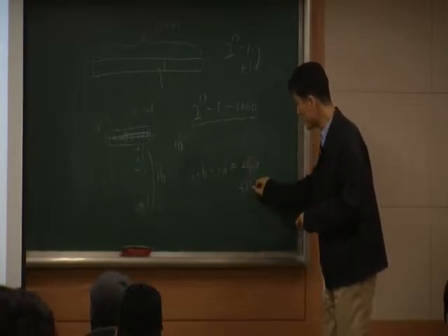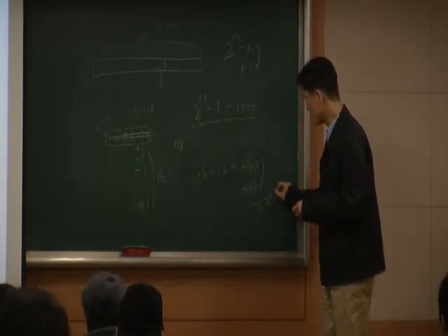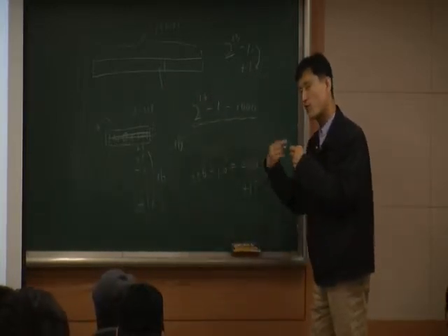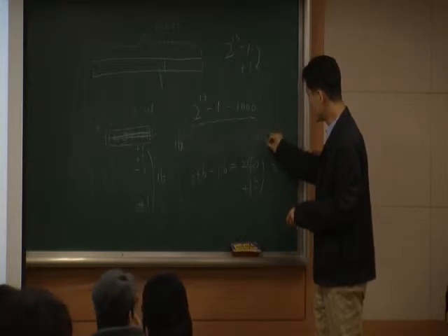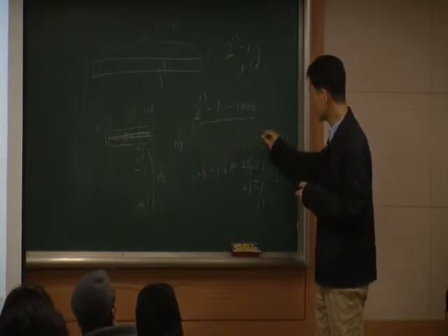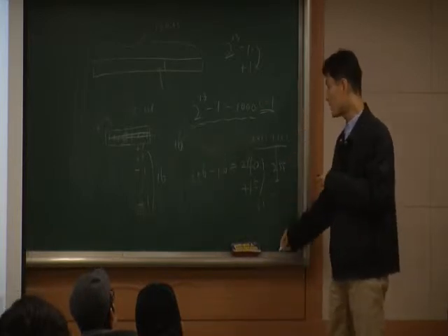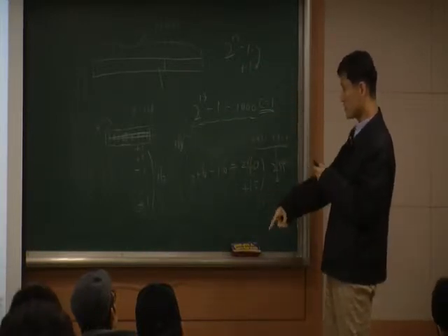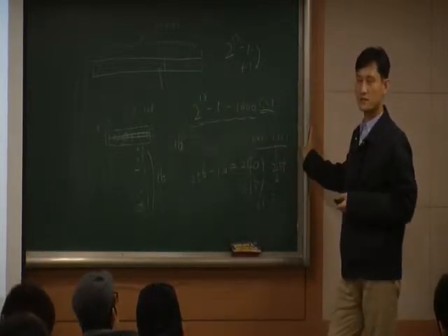So once you have 16 pulses coming in, then the value remaining here becomes 256. Let's say we have 15 pulses coming in. Okay, so far we have 15 pulses. Then the value inside here becomes 255, which is 1, 1, 1, 1, 1, 1, 1, 1. And one more pulse coming in, now this value becomes all 0, and now we have a carry on. That's how exactly we can count 16 pulses. Because by watching the carry, once the carry flag is on, that's the time that we have 16 pulses.